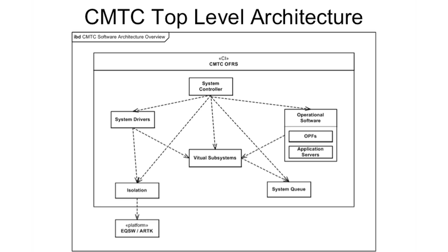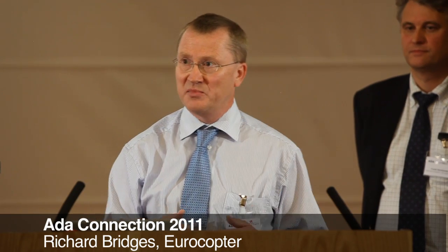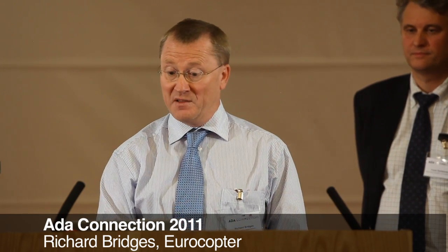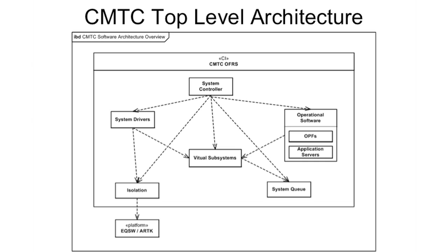The virtual subsystems are effectively a global data object. They abstract the subsystems within the avionics system, so you'll have a navigation virtual subsystem, and there's a data representation of all the data that is needed by these computers. The system drivers don't know anything about the operational structure of this data.